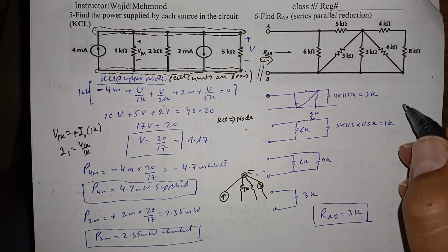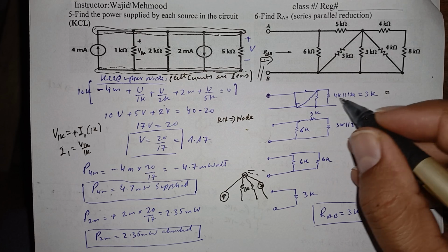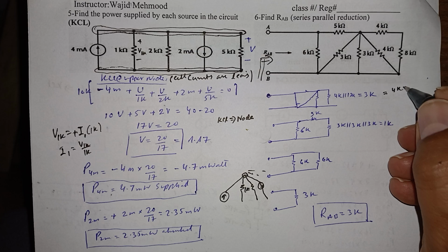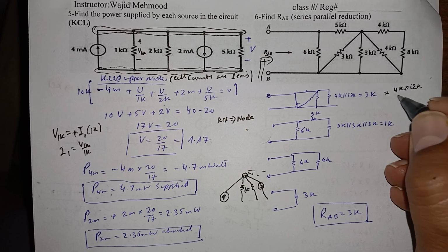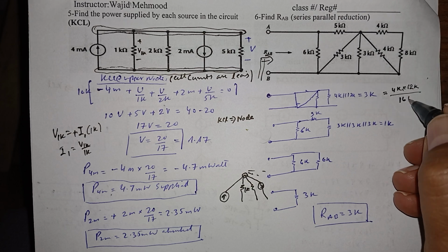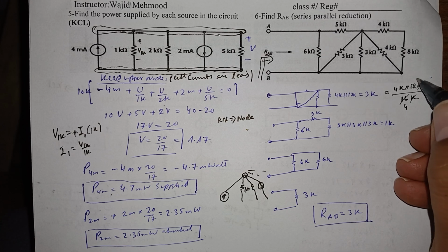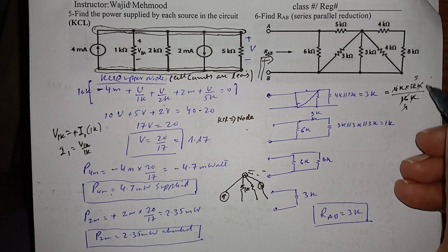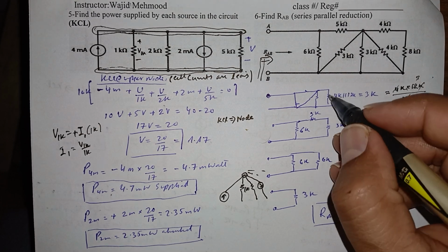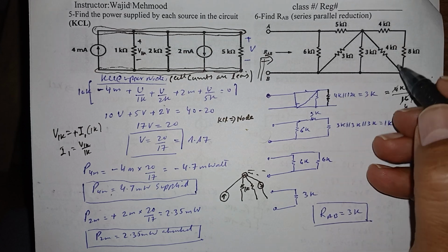that the parallel combination can always be found by their product. Means if I want to find the parallel combination, it would always end up into their product divided by their sum. 12 plus 4 is 16K. So 1K is cancelled. 4 3s are 12, 4 is cancelled, 4. This is 3K, which is shown here. So this one is actually 3K reduced between these two nodes here.